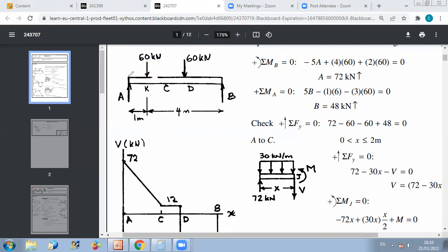The first section, as we discussed, just let us see how many sections we need before proceeding with each section separately. And again, keep in mind to determine what are the sections you need. You never work with transformation of distributed load into one resultant force, because as we discussed, the shear and bending moment will completely change if you replace a distributed load by a concentrated force. You can only do the replacement when you are calculating external reactions, or when your section is not passing by the distributed load.